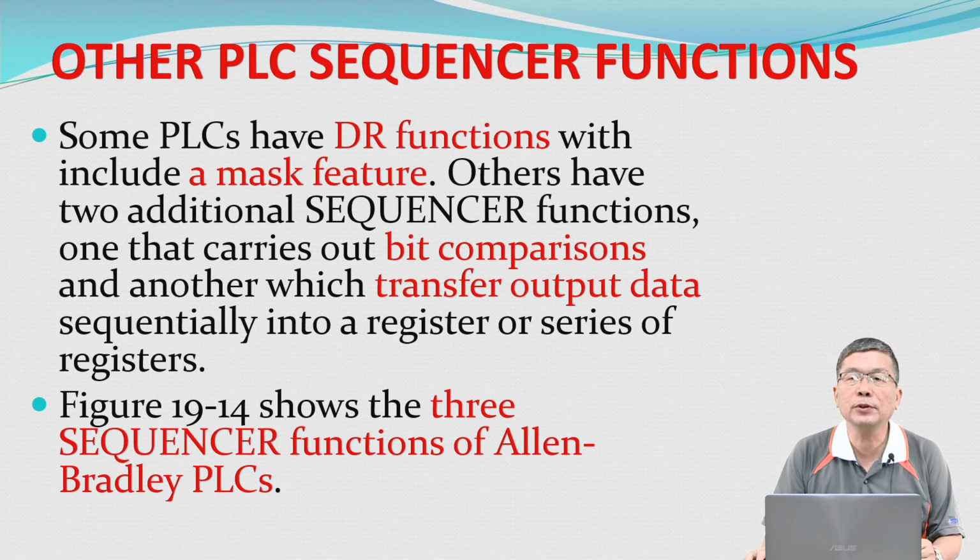Others have two additional sequencer functions, one that carries out bit comparisons and another which transfers output data sequentially into a register or a series of registers. Figure 19.14 shows the three sequencer functions of Allen-Bradley PLCs.